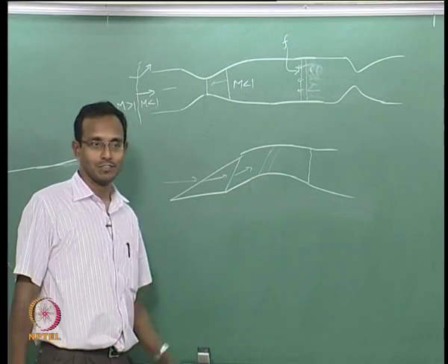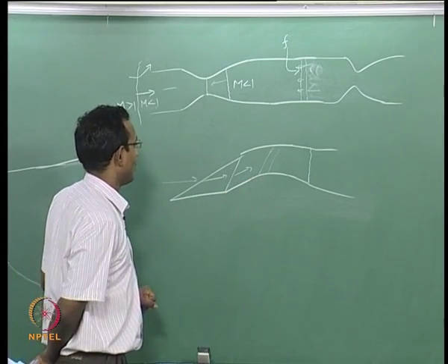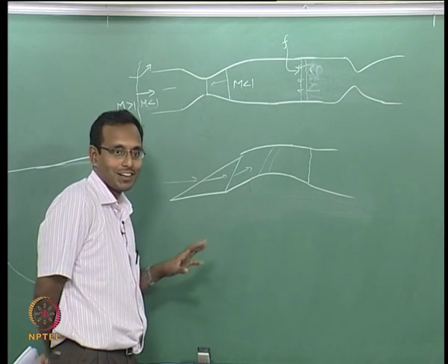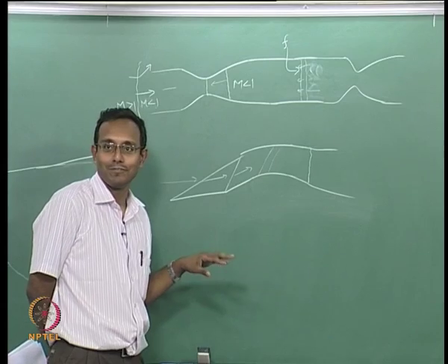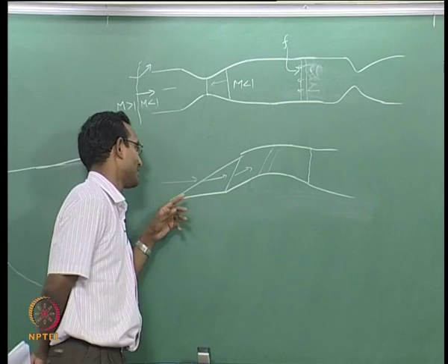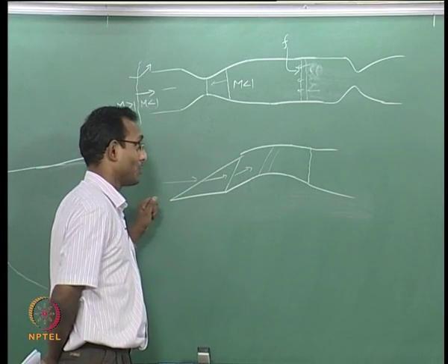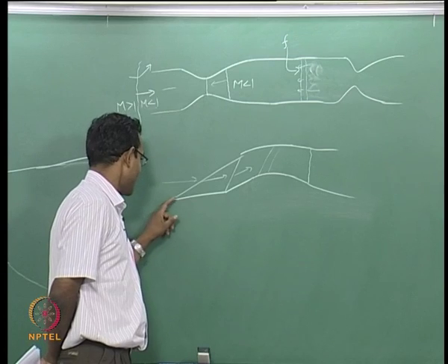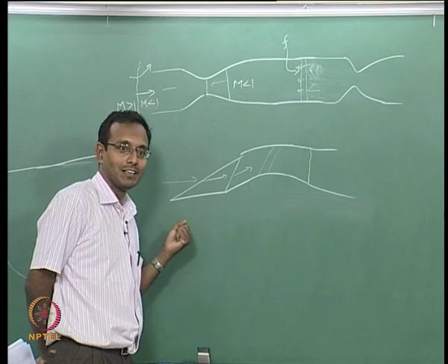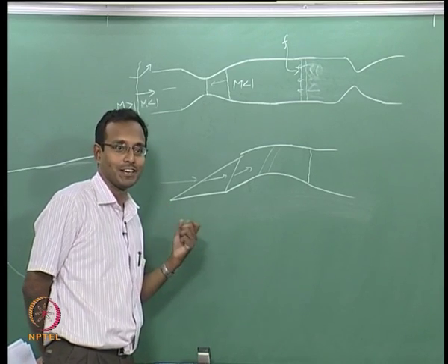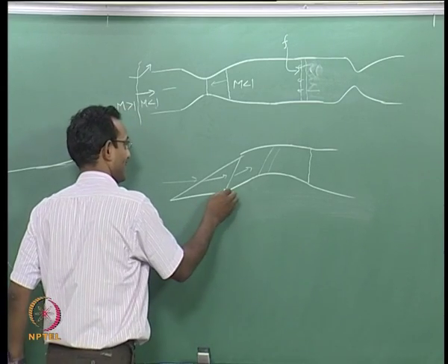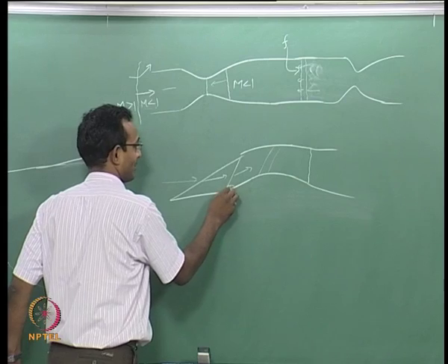If this is the situation, now there are more things that can happen in here. I will just tell you this is not in any way part of the scope of the course. I just want to go a little beyond, since we have this 5 minutes. Because of this sudden jump in pressure, the boundary layer can now suddenly face an adverse pressure gradient and it may separate, need not separate, it may separate. There is a possibility that it separates typically in this one.